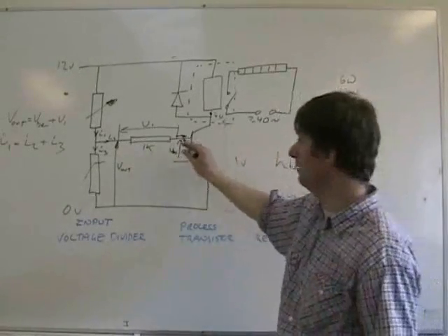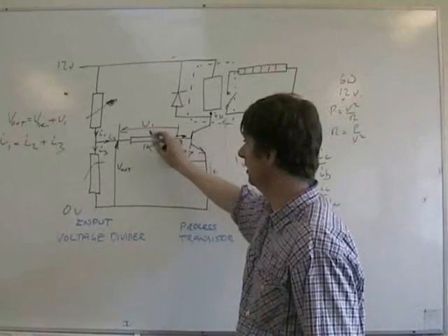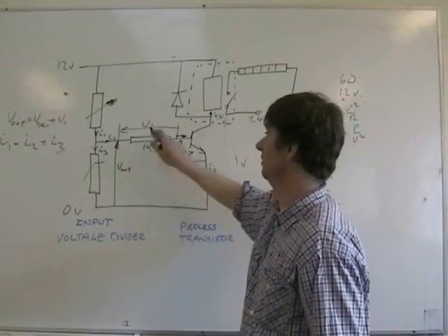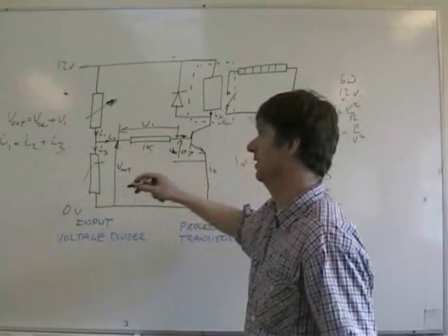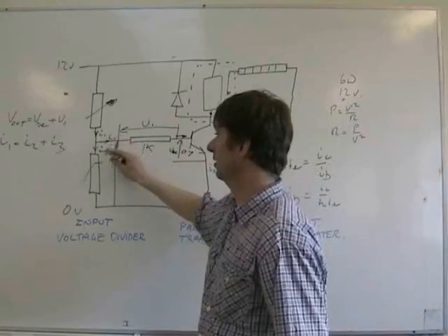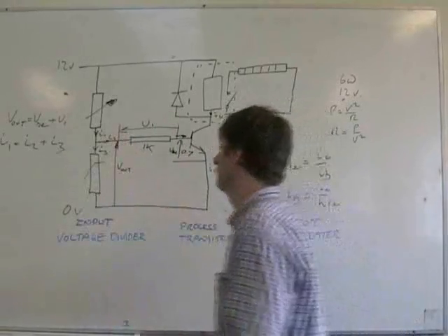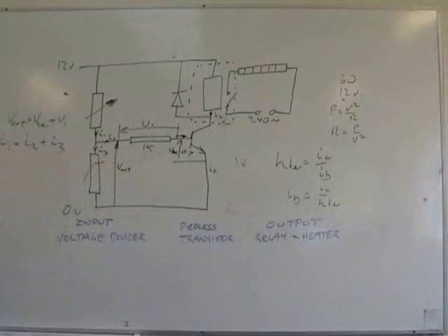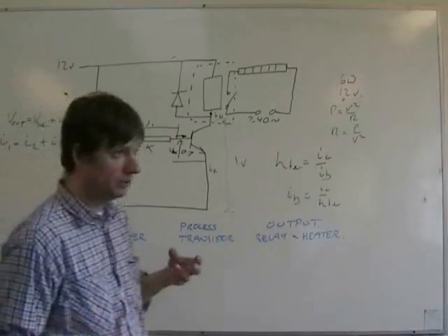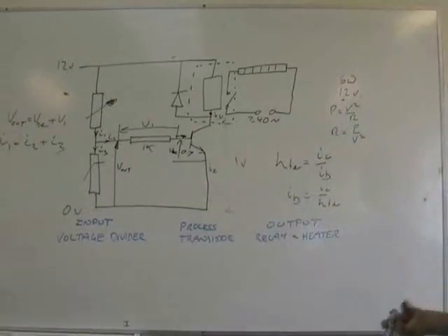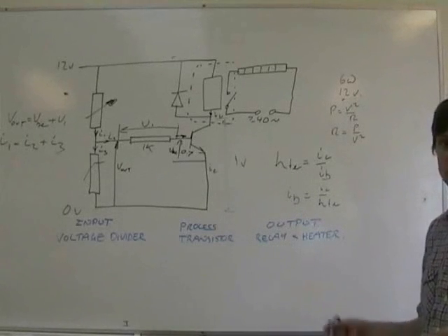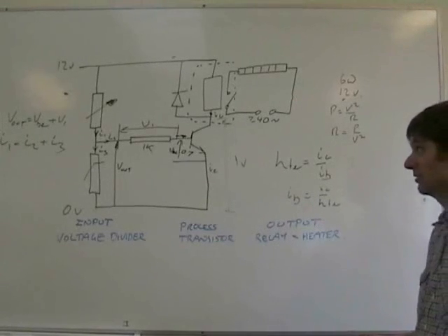Once you have the current there, V equals the current times the R, so you get that voltage. So we now know V out. We know that current, you can work out that current. These questions, it's just a case of looking at where you know either the voltage and the resistance, when you know two out of the three, and then calculating the third one, and then that will feed into something else.